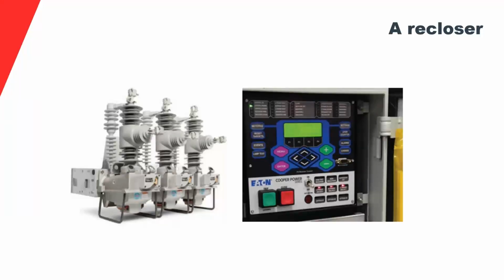Right now, modern reclosers have the ability to sense both currents and voltages, and not only that, they have the capability to sense voltages on both sides of the breaker, so that they can perform synchronizing functions or voltage induced functions for automation in the system.